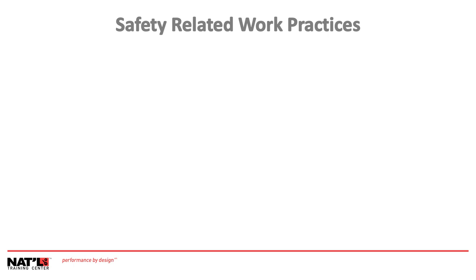If you'll look with me at section 3.2.1, we're now going to look at safety-related work practices. Safeguards for personnel include the consistent administrative enforcement of safe work practices. Safeguards include training in safe work practices, cell line design, safety equipment, PPE, operating procedures, and work checklists. Articles 310 and 320 of NFPA 70E alone are inadequate to protect personnel working on cell lines properly. This training is based on National Field Services cell line practices and in some areas will be more prohibitive than these articles.